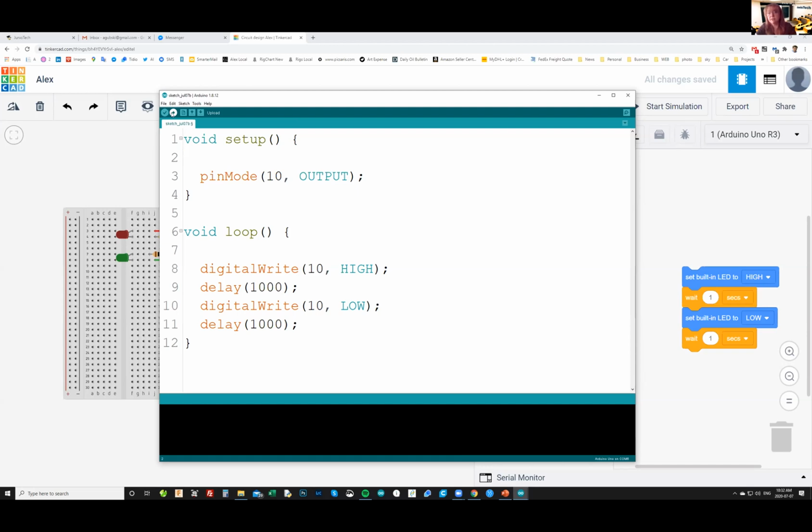That's a button, the second button there that Alex just showed, the arrow button, that will download your code to the Arduino, and voila, your Arduino will right away start working. Just so that you don't get frustrated with this process every time, Tinkercad helps, because you can test your ideas there. If your idea worked there but doesn't work on the Arduino, you understand that maybe some wiring was done wrong, and you can follow your schematics.